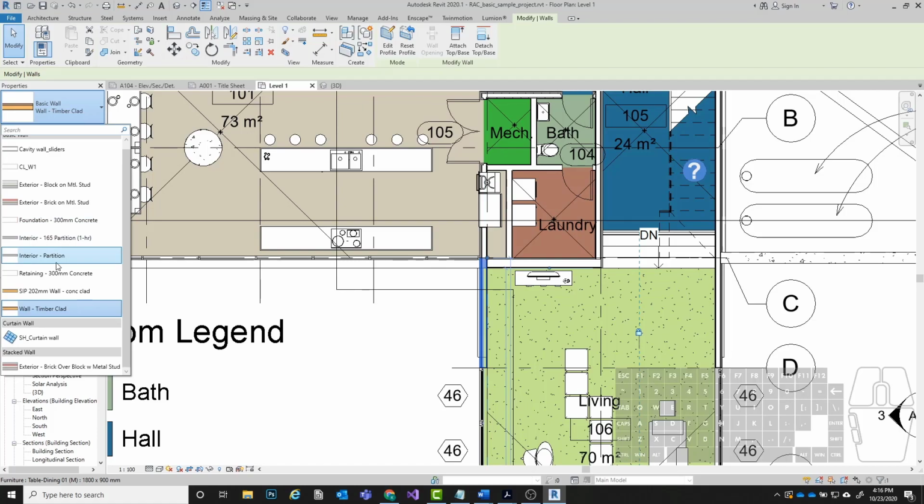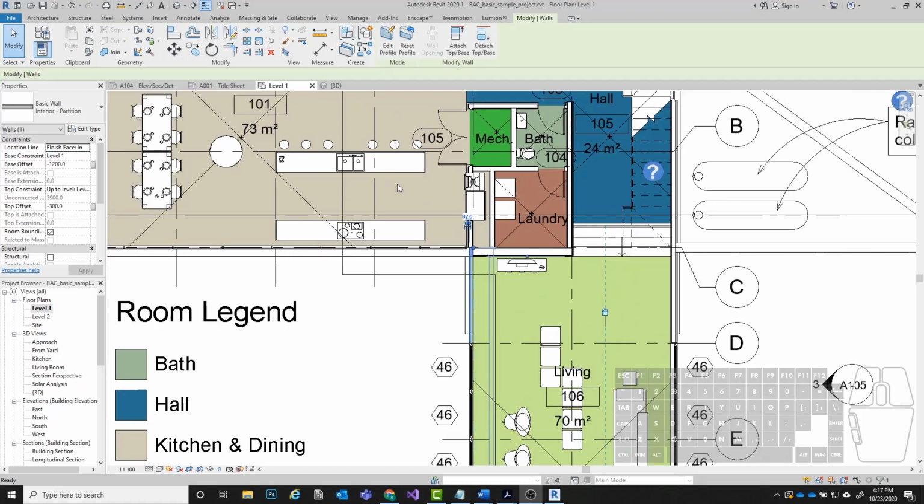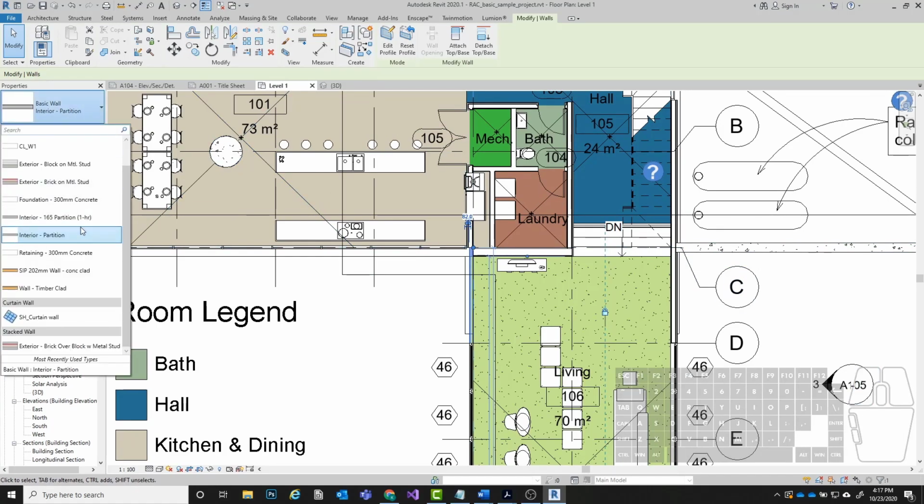So different walls require different thicknesses. If you have a wall that requires plumbing, that's probably going to be thicker than just a normal wall. So just a typical wall is going to be around 4 7/8 inches in thickness, okay? So in the AutoCAD project, we represent that as just a 5-inch thick wall, but in reality, it's closer to 4 7/8 inch of a thickness. But you're going to have to set up different wall types and use them.